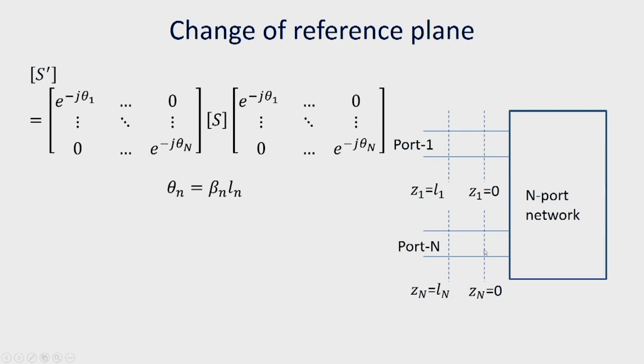Similarly, for the Nth port, Zn equal to 0 will be here. Now, many a time, the evaluation or measurement of S parameters is not possible to be done at the reference plane where we want the S parameters.